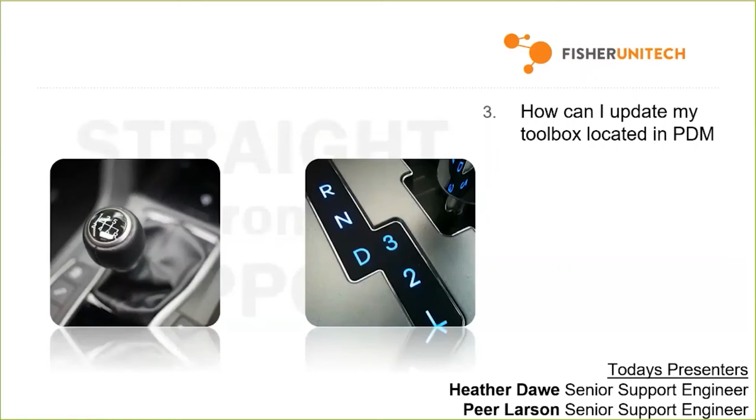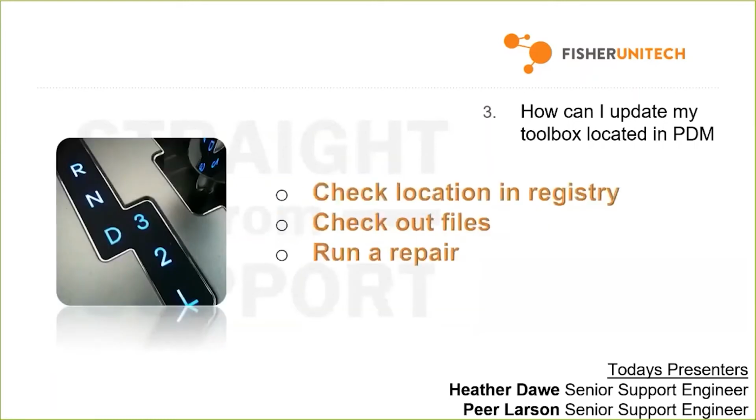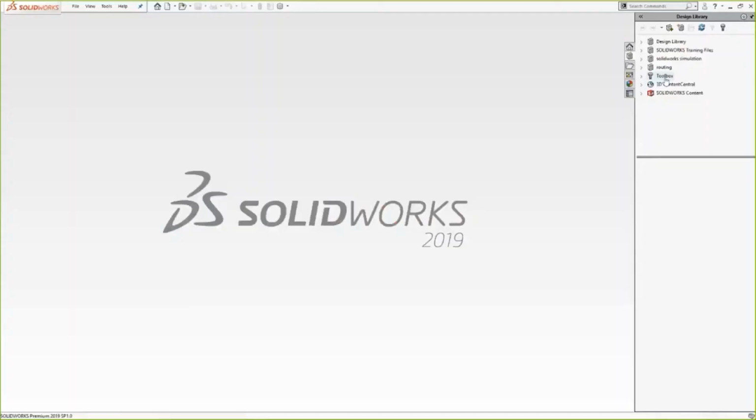It can sometimes be a little bit more finicky. It needs to completely be run as admin, things like that. But this automatic way is done using a repair, but with PDM, there's an added ripple of us needing to check out some files before we go through and do that. So I'm going to cover the automatic method first, and really there are 3 steps. We check a location in the registry, we check out specific files, and then we run a repair, and after that, it should update it, and then some ending steps, which I'll talk about post-upgrade.